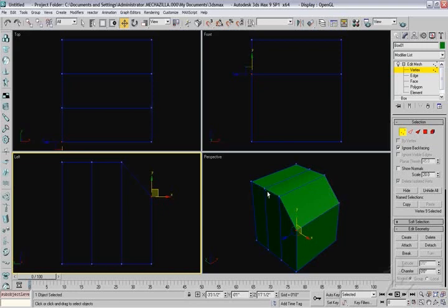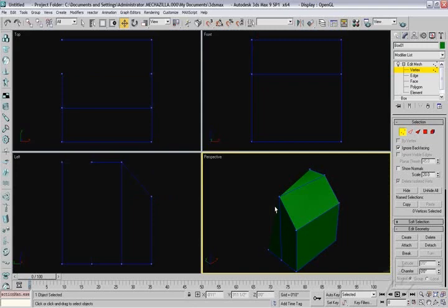Now, one of the things I want to point out is we can't just simply go along and select a vertice and delete it, because you will lose your support of your geometry. So instead, what we do is we do something called welding our vertices, but we'll get into that a little bit later on. So in this case, we had this model and we pre-segmented in the left viewport here,